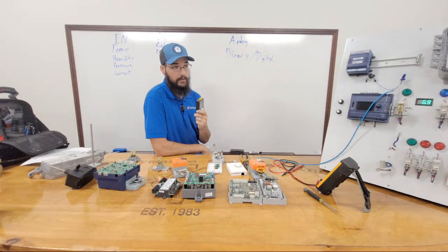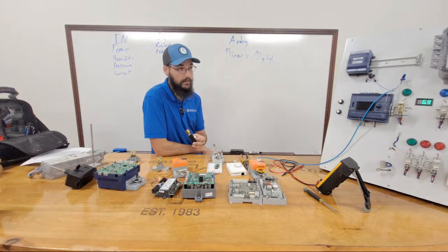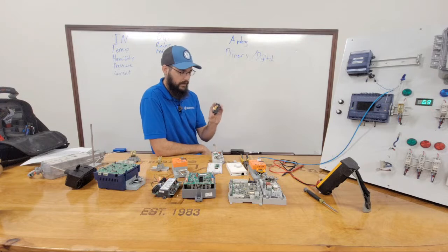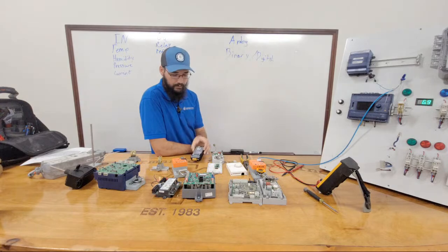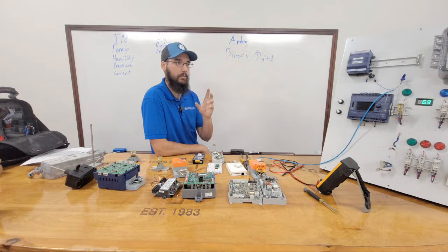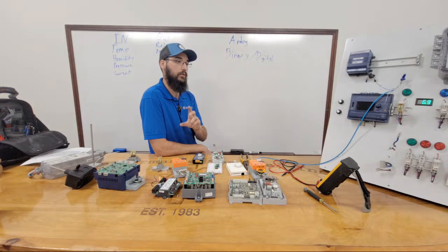If you have a system that's running a milliamp signal, and you need to convert it to a 0 to 10 VDC, this is something that ABB used to have us do. I think they built it actually into the drives now or something to that degree. Anyway, you can take and put a 500 ohm resistor between the input and common or ground terminals for a milliamp signal and convert that signal into a 0 to 10.